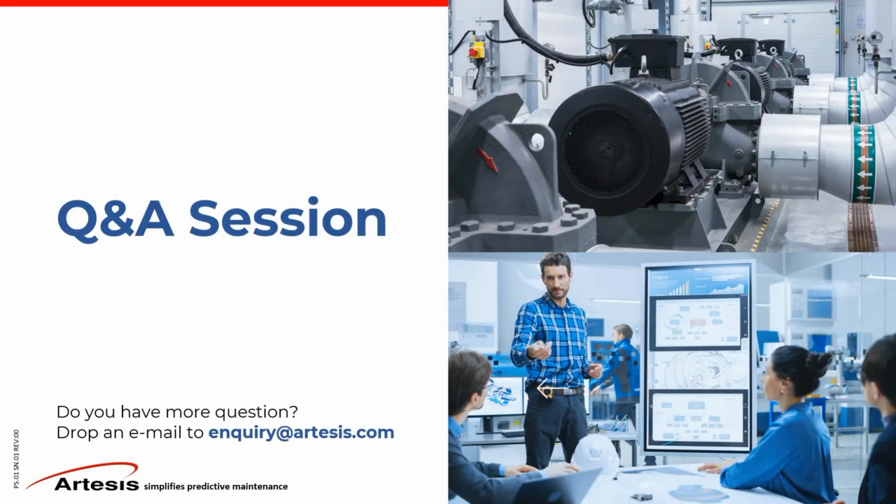Okay, I think there are no more questions, but in case there are. On the chat box, Leonardo asked, what is the alarm setting for crest factors? There are no alarm factors, but we are using a standard sort of range, and that depends whether the machine is driven by a VFD or it's a non-VFD driven system.